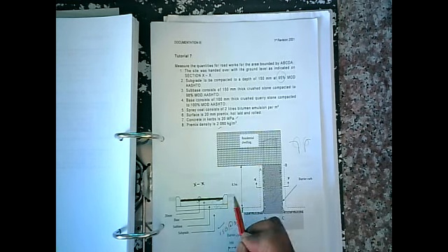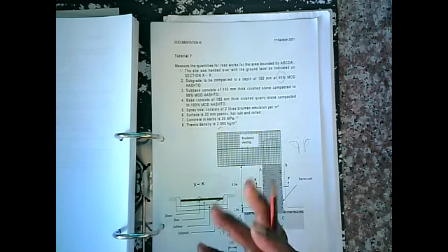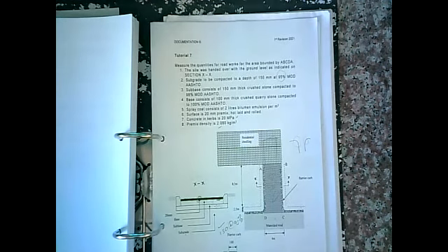All right. So this is the dimension of the curbing, right? You may be wondering why. We're going to need this, right? And the curbing basically ties in with the municipal and climbs all the way there on both sides. All right, and now interesting enough, if you look, subbase and subgrade sit below the curb. So the base area is going to be smaller than the subbase area and the subgrade area, because it's confined within the curb, which has a thickness of 180. All right, so that's basically how you look into this drawing.